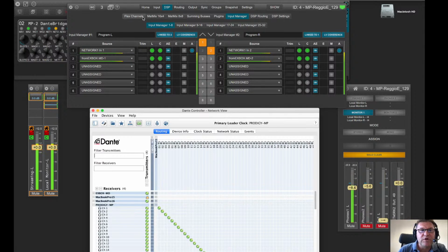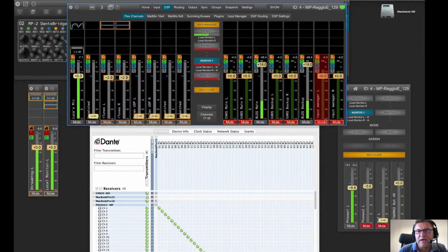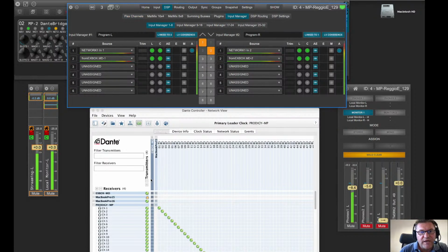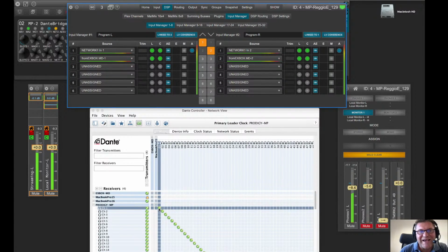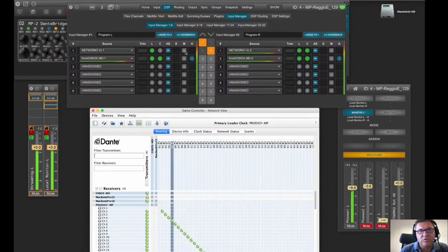Now, I'm going to go back to the flex channel and mix that into the feed towards the streaming of this webinar, so you can really listen to that. I'm unmuting this, maybe reducing the volume a little bit, just to have the possibility to talk on top of that. I go back to the input manager and I remove one of the patches. Dante is not failing, but audio is not getting there. Boom. The audio coherence is not there any longer.